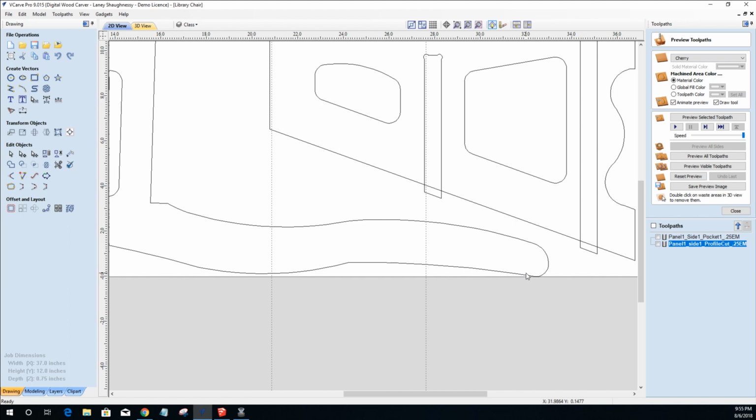I will have the CNC, with an 1/8 inch bit or something, pre-drill those holes. But I will use my hand drill and my countersink bit, and then out of some scrap wood, I'll use my plug cutting bits on my drill press or with my hand drill, whatever, and I'll cut a couple of plugs out of it, so it's matching the grain. The plug cutting set has kind of a taper to it, too.